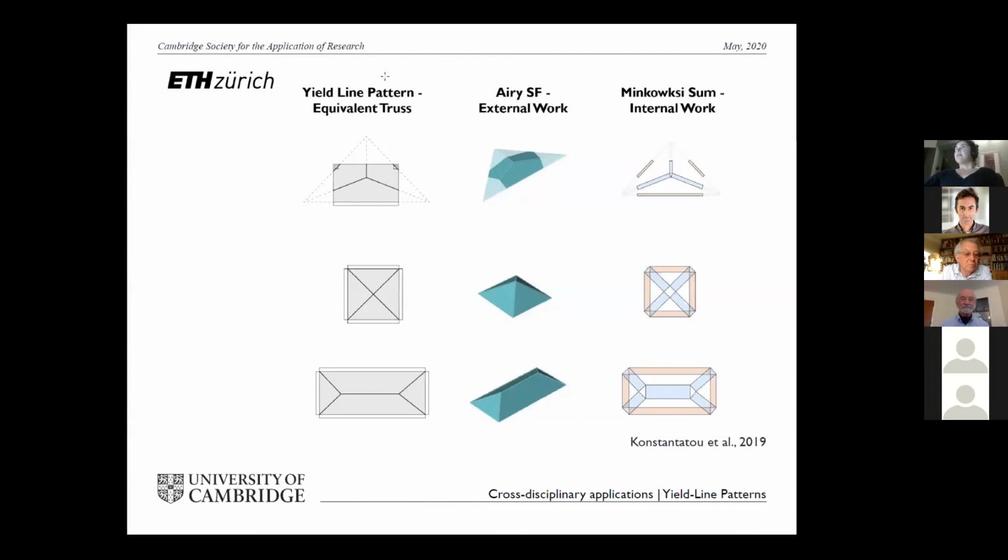So all this geometrical framework based on reciprocity between form and force diagrams and the reciprocal stress functions can give you a very visual and intuitive way of understanding how to design and analyze structures, and hopefully in a way that both architects and engineers can understand and communicate with each other.